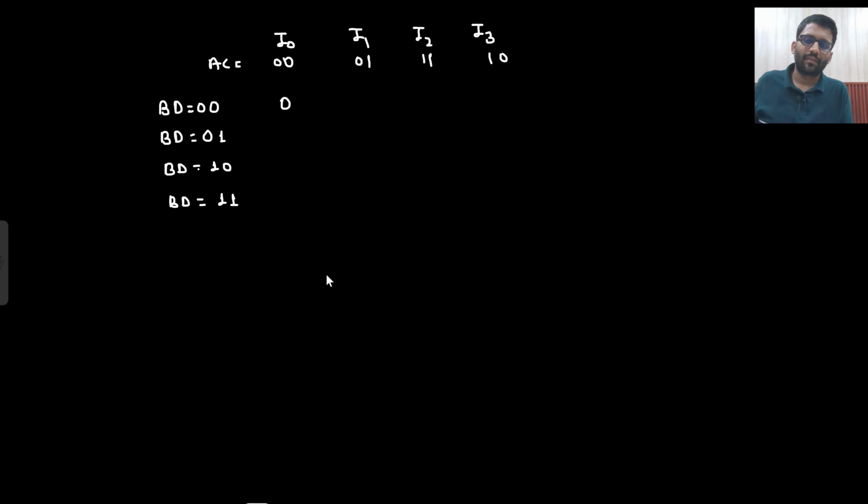So BD is in our control. BD can take values 0 0, 0 1, 1 0, 1 1, and these are I0, I1, I2, I3. What about AC? 0 0, 0 1, 1 1, 1 0. So 0 0 0 0 will be 0. Now ABCD is our function.